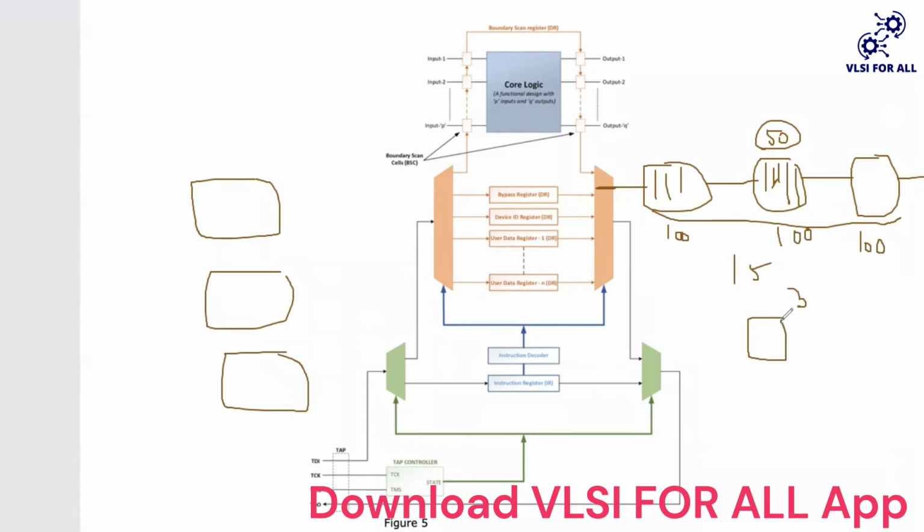If you do it in parallel, how many shifts do I need to do to control the 50th bit of this one? 50 only, right? So that's the benefit. That's why we cannot connect all the JTAG registers in a serial fashion. We need to do it in parallel for multiple registers which are not dependent on each other. So that's why we need a demux logic over here.